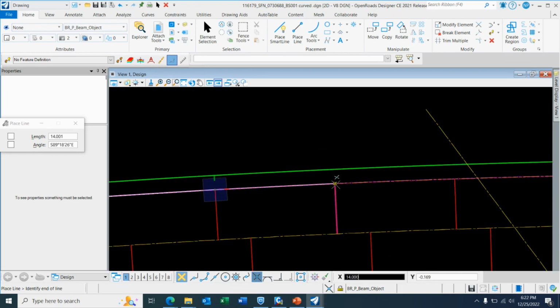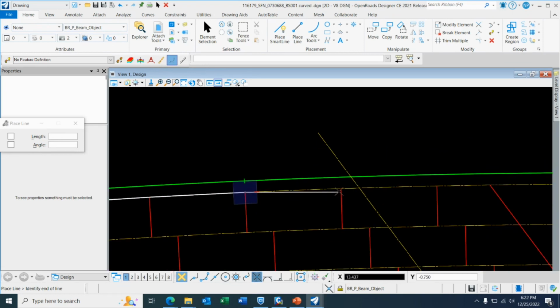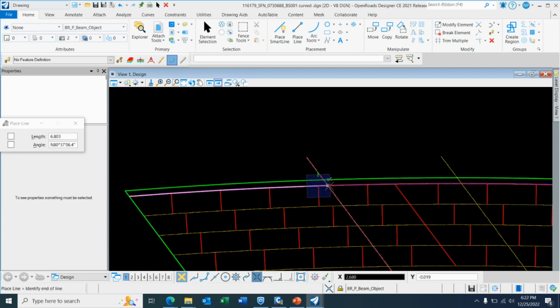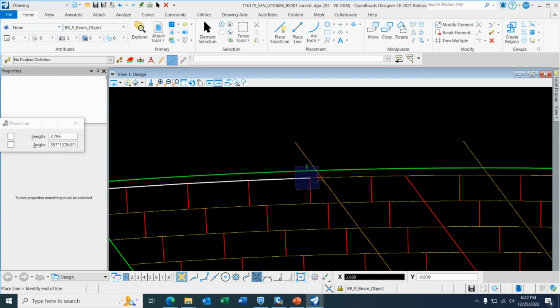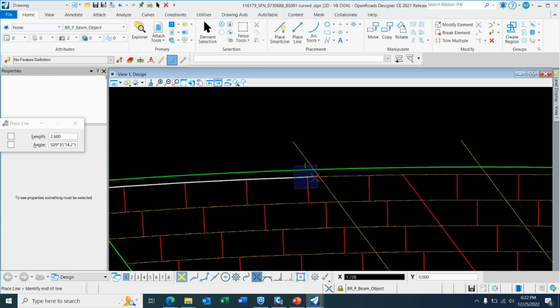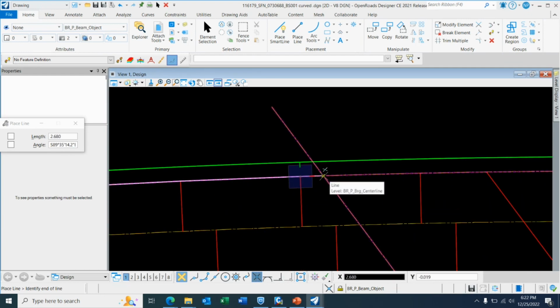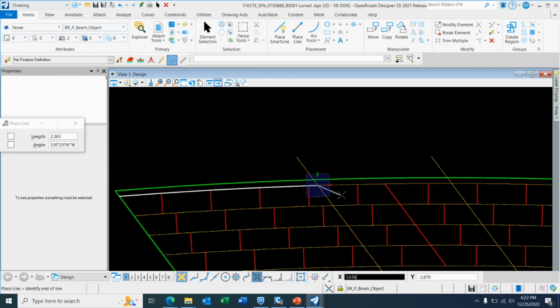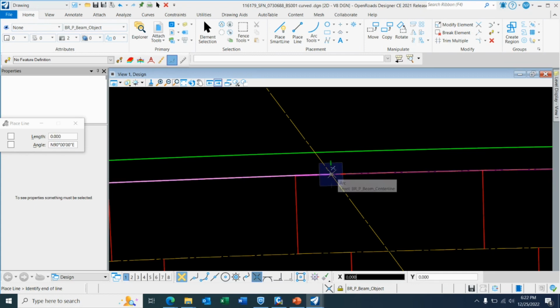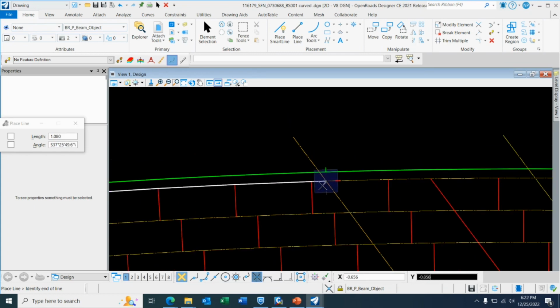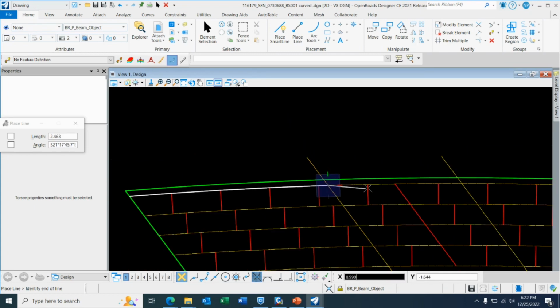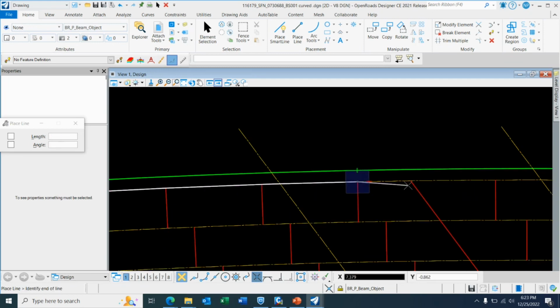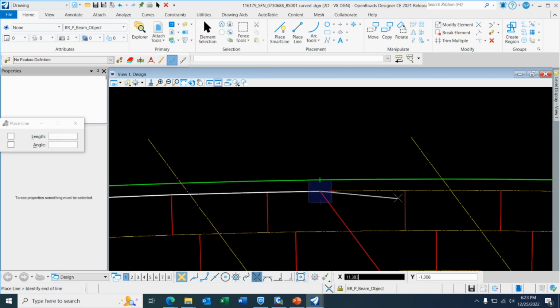That means I will just basically draw my straight beam elements between the points where I want them. And this is another reason I kept the splice location, because I want a node at this point so that another element begins here and I can have a different section for the negative moment region. And like this go on.